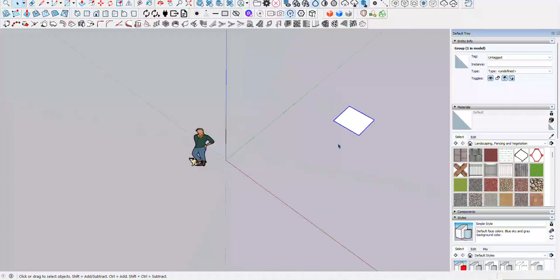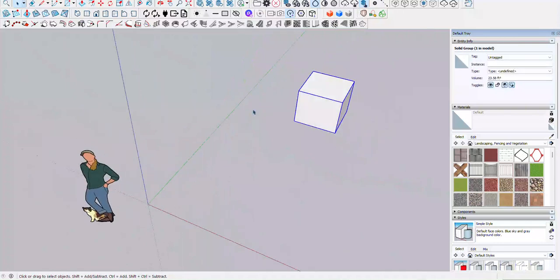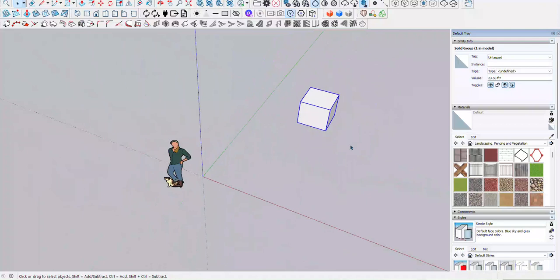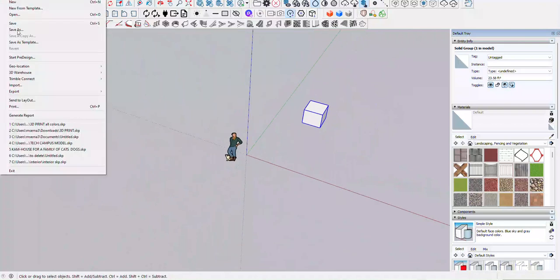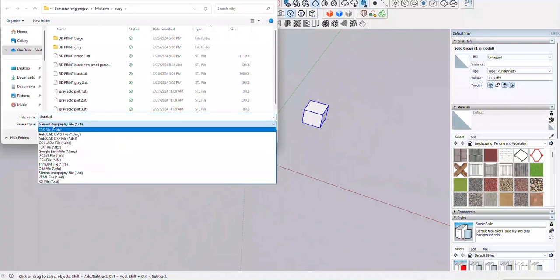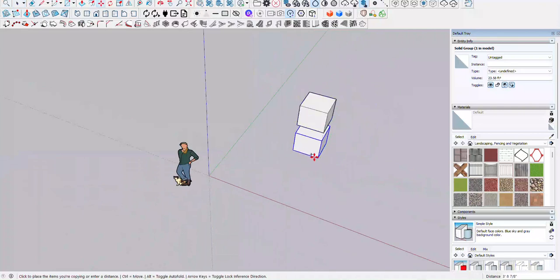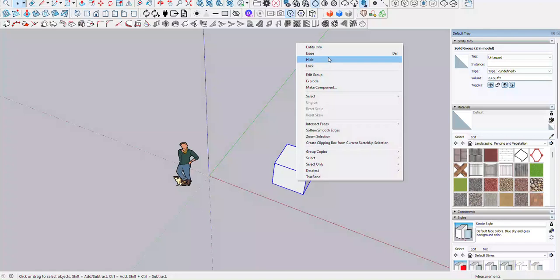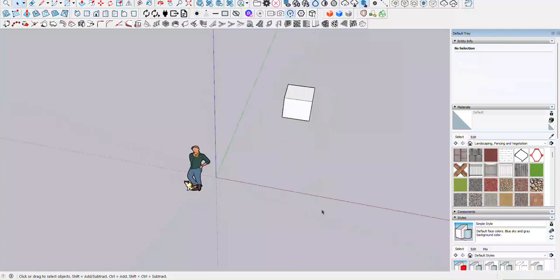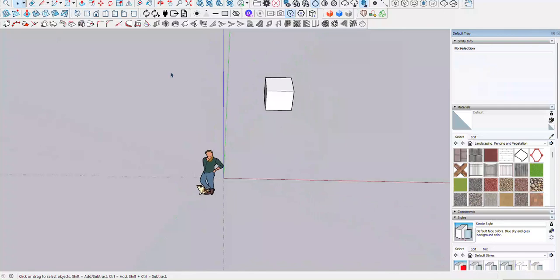And so when it comes to SketchUp, remember when you're 3D printing, let's say I already scaled it down to whatever I needed to do. And the way to export it, all you have to do is File, Export, 3D Model, and you will select your STL file. You have to be sure that everything that's seen there is going to get printed. So let's say for some reason I want to hide this. Even though you press hide, it's still going to be detected as an object when you do STL out. So be sure to delete anything, create a new file, and delete anything that's not needed, right?